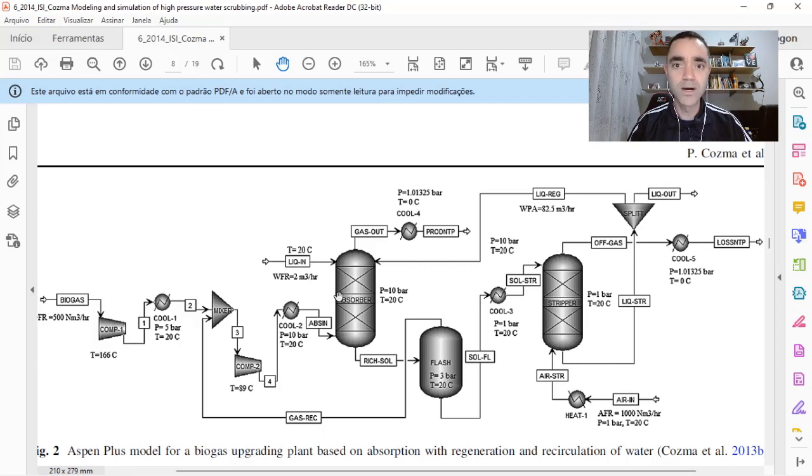And to do that, one of the most important things, or the first thing that you must do when you get a new process to evaluate, a process flow diagram, a heat and material balance, is look for consistency, or if there are any inconsistencies in your documentation.